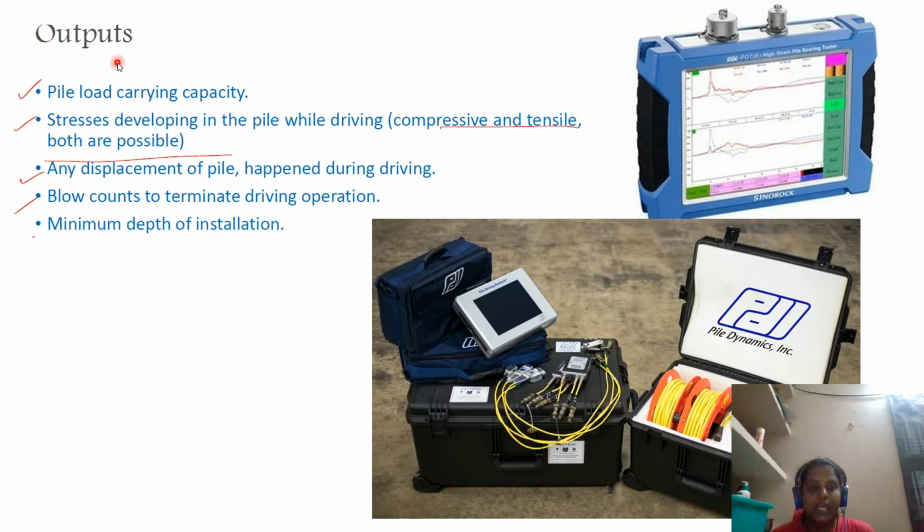So what could be the output? As I said, pile load carrying capacity. We would have calculated the pile load carrying capacity from the soil properties and the cross section. But once you install your pile, especially in the case of bored cast in situ, you are not sure about the cross section, whether it has formed perfectly. So the output is going to be the pile load carrying capacity, both in terms of end bearing and skin friction, and the stresses developed in the pile during the driving operation.